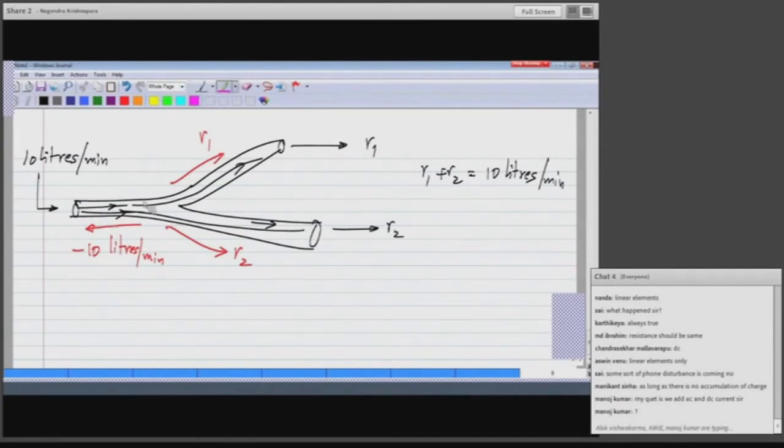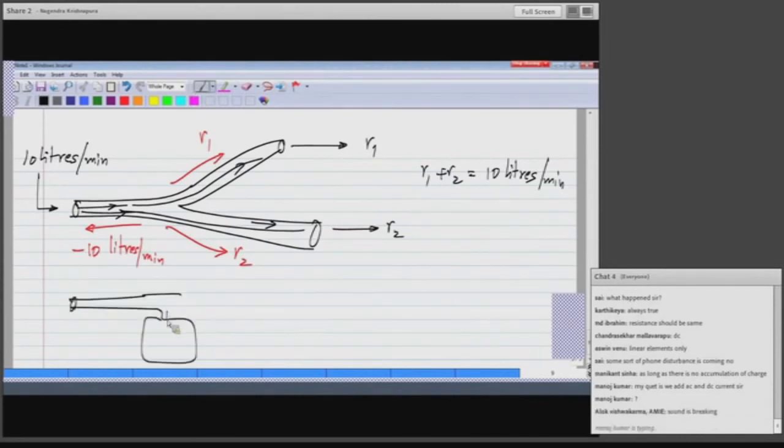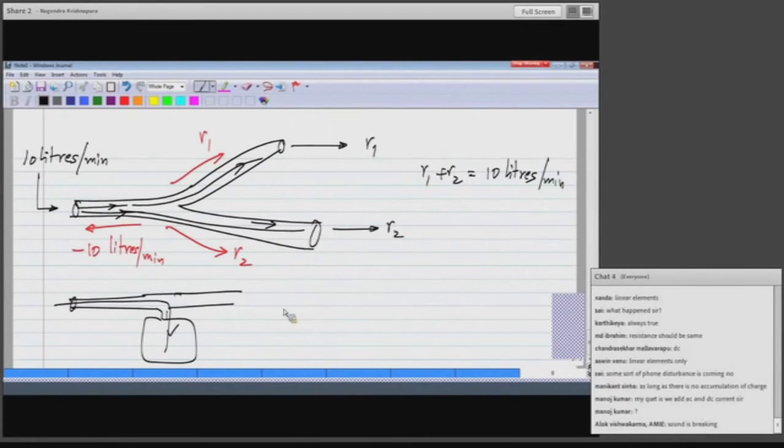And I will measure the voltage across each one. Like I said, voltage is the potential difference between 2 points. So here I will measure V1 in this direction, and here I will measure V2 in this direction. Please mind the directions in which I am writing this. V3 here, V4. You see that I am taking all the differences in the same direction, and V5. Again, this has nothing to do with the specifics of the circuit, and there is a law that says that V1 plus V2 plus V3 plus V4 plus V5 equals 0.